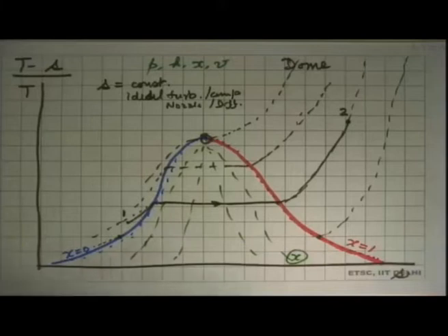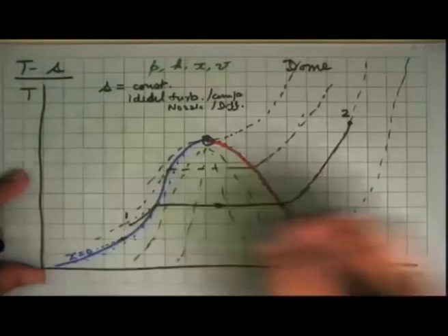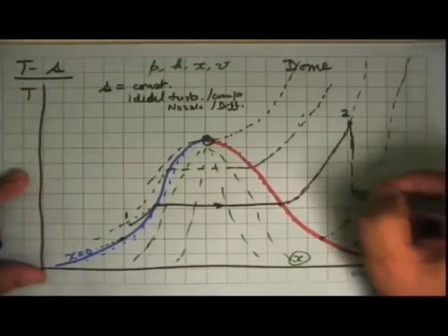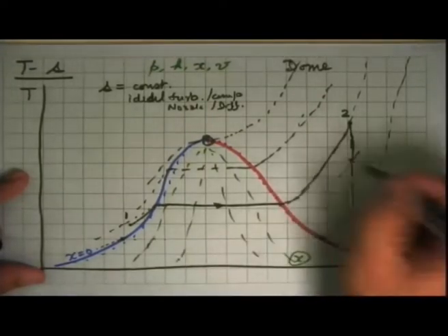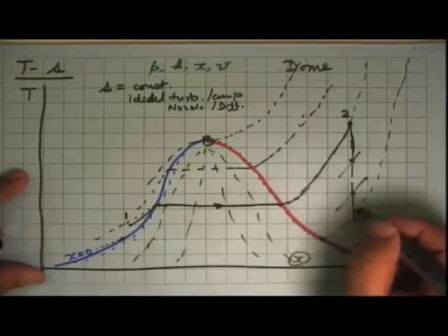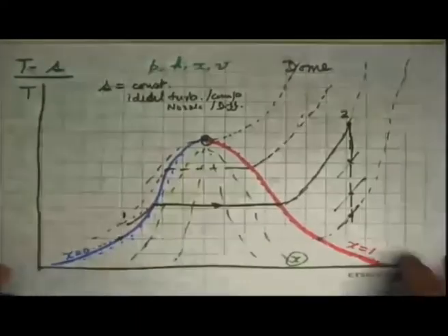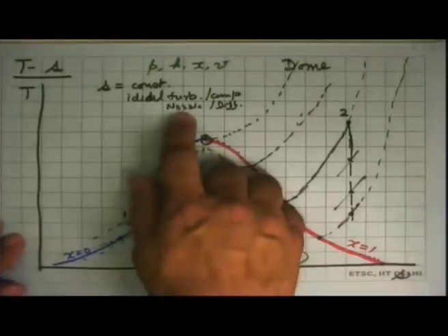But that doesn't matter. So what it means is that if S is constant, a turbine or a nozzle attains states which are on this line, anywhere. And then depending on if the pressure was there, this will be the state. The pressure was there, this will be the state. Pressure was there, this will be the exit state. And this diagram tells us that if any of these devices were non-ideal, that's what we learned in the laws, then there will be an increase in entropy.